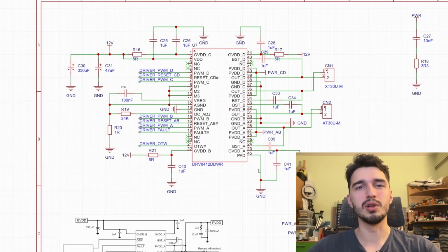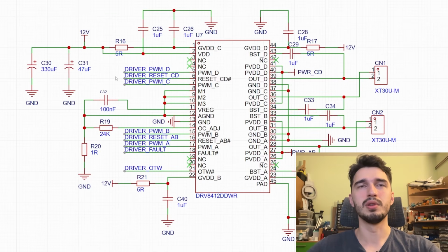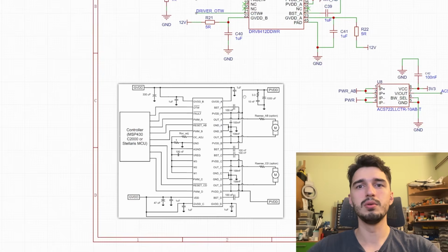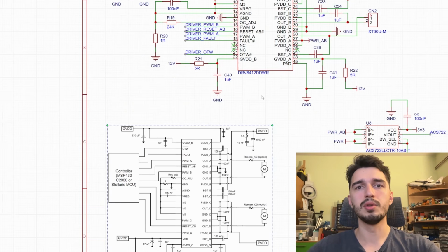Time to look at the electronics. So we're going to start with the schematics and then go over to the PCB. And let's begin with the motor driver that you've seen me pick. So these are all of the components necessary around it. I won't go into too much detail. How I do something like that would be to find their typical application reference design in the datasheet and follow along with all of the recommended calculations, component placement, component choices, and so on.